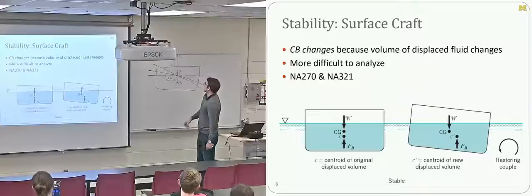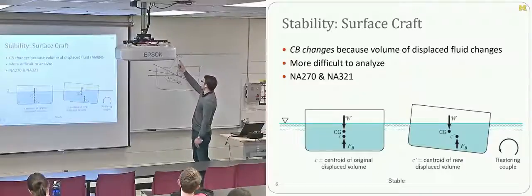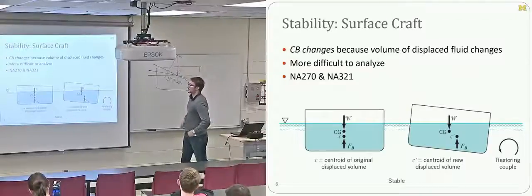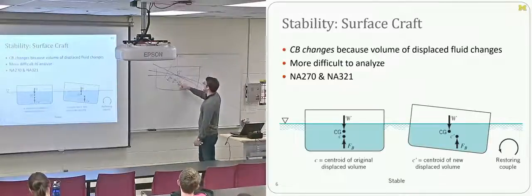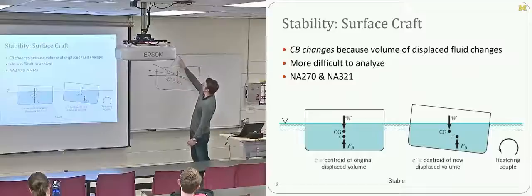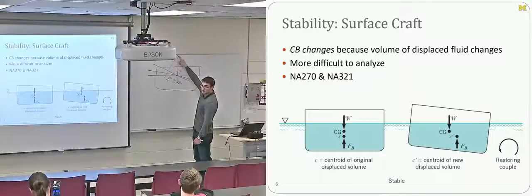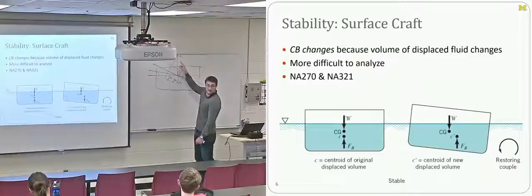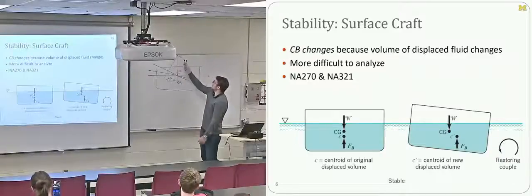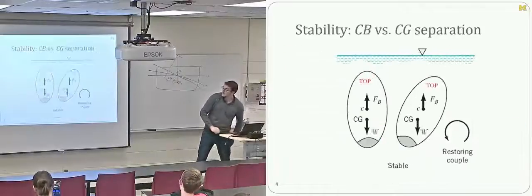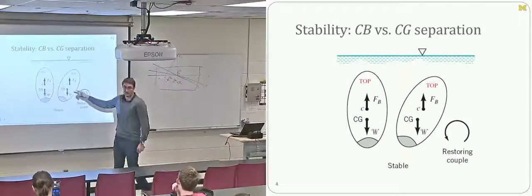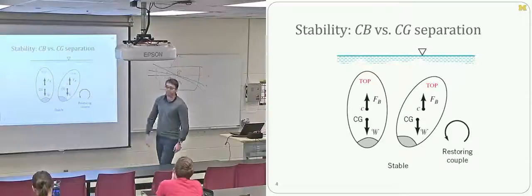And so the point here is that if that buoyancy always acts through the metacenter, then you can essentially, at whatever roll angle the ship is experiencing, or whatever keel angle, move the buoyancy force to the metacenter without changing the torque on the vessel, or the moment on the vessel. And what that means is, as long as your metacenter is above your center of gravity, then you, in essence, have a case like this, where it's going to act to restore a non-zero heel angle.